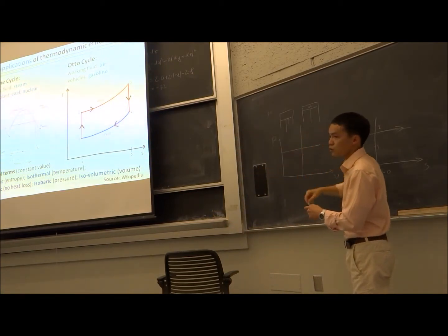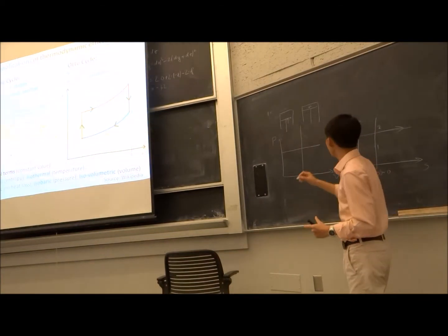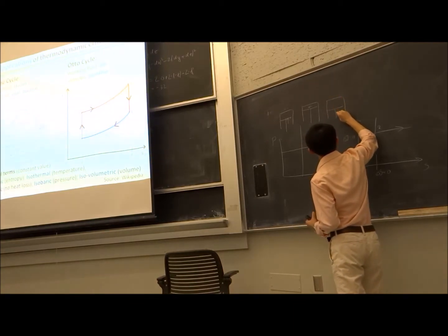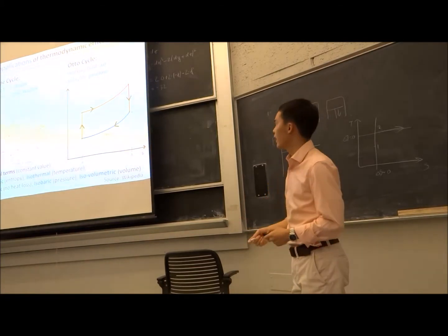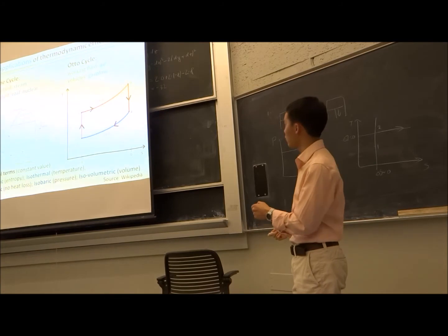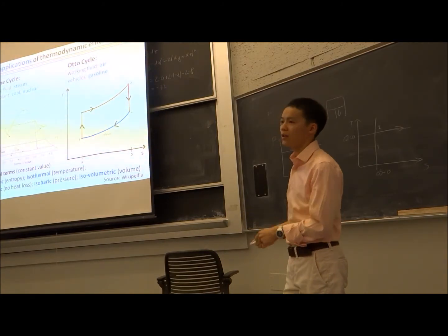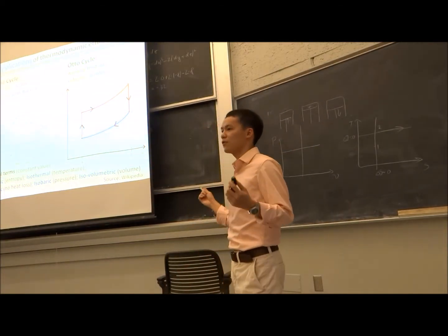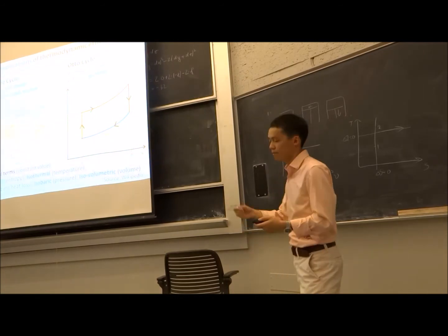And then after you have this very hot and high pressure air mix there, it will drive the piston down to drive your wheels, etc., providing the work. And that is, as you can see, the isentropic process from 3 to 4. And then we normally just connect 4 and 1, so it's a closed cycle. So that's it. That's the Otto cycle. That's how it works in a